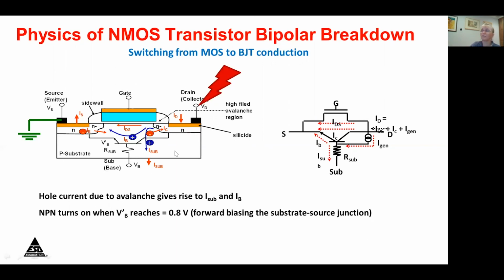The other feature here is that in an ESD condition, the discharge event is very fast. It's a sudden event, a short duration event, with very high current, and the voltage is clamped by the device itself. But it's not a repeated event that you're going to see continuously every cycle while you're operating the device. It's an unlucky event, but you have to plan for it. So the behavior of the device and the modeling is more in a very short time domain rather than a 10-year lifetime consideration.